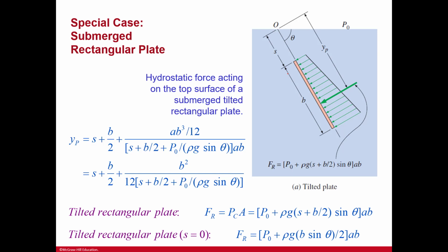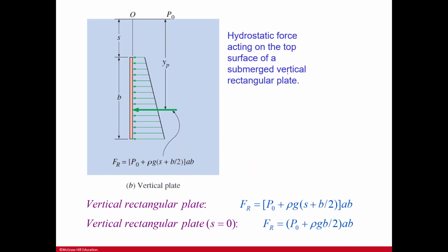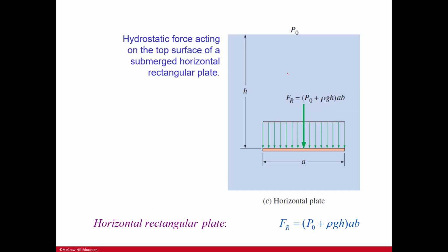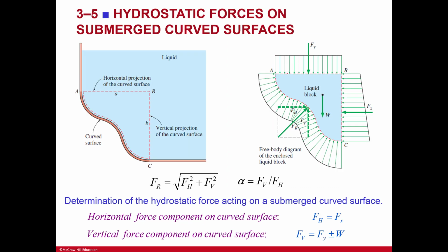There is also a special case, as there always is. It's the submerged rectangular plate. And we have these formulas here. Hydrostatic force acting on the top of a surface of a submerged vertical rectangular plate. Here's more. And hydrostatic force acting on the top of a submerged horizontal rectangular plate. And again, more. Very simple, pretty simple equations here. Hydrostatic forces on submerged curved surfaces, again, just letting you see where the geometry is in the curved surface.